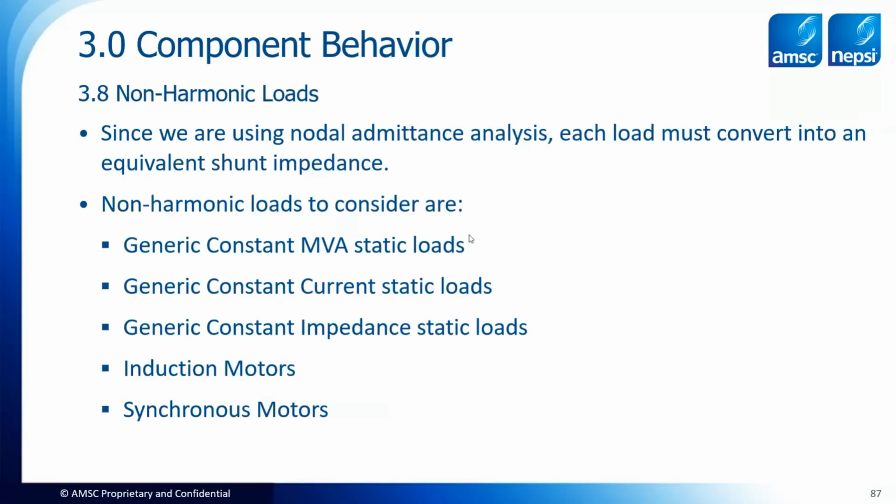So for non-harmonic loads, you could go nuts trying to figure out exactly what you're supposed to do here. But what we typically do for our modeling is we consider them as constant MVA, constant current, or constant impedance loads. Those are the most typical load models used in analysis programs. And then we also have 2 categories, induction motors and synchronous motors, that I would like to address.